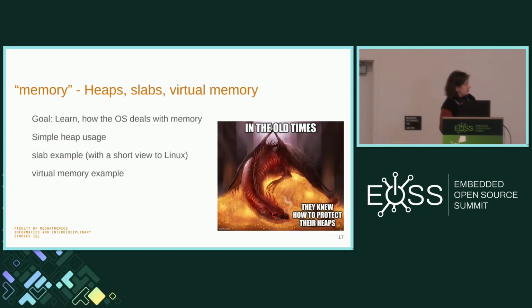So this is the next part. And then we need to talk a lot about memory. Because again, if our students have some experience, they are mostly experienced in application level programming, maybe JavaScript, maybe some Python. So we need to go in detail to explain at least the data structures used to reserve the memory, but also to explain that in Zephyr, you have no memory protection. You really need to think about it a lot.